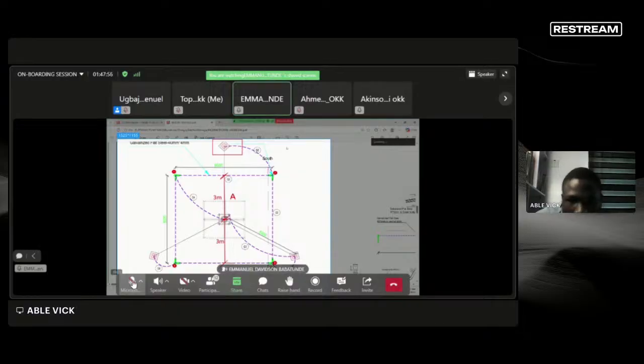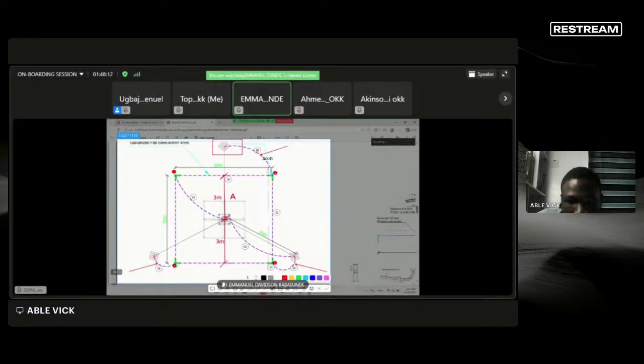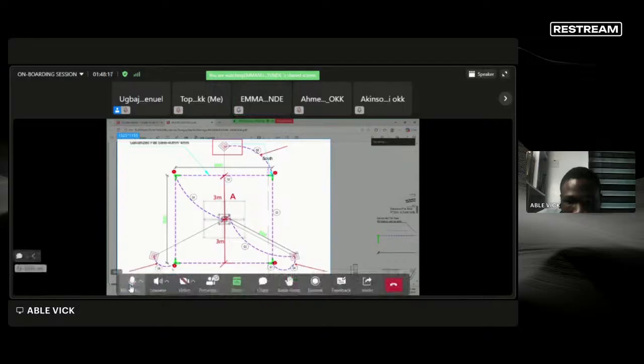So if you look at it from this picture, look at the flat bar here. Look at the other flat bar here. Look at the other flat bar here. So they need to come out of the ground from the 2 meter where you install them and connect to the earth. You can see their connection points. So the ring also needs to fit the tower leg. You need to connect to the ring and terminate it on the tower leg for it to complete your earthing installation.